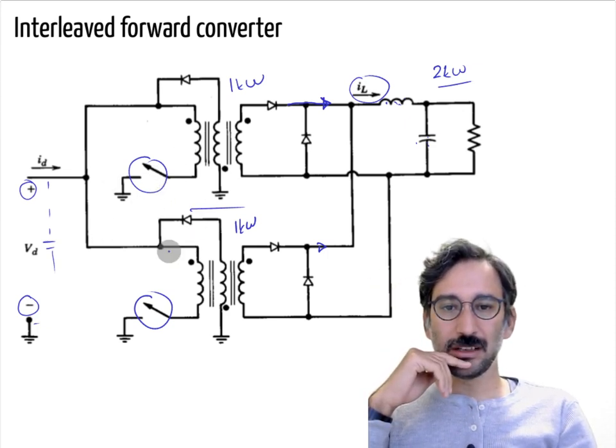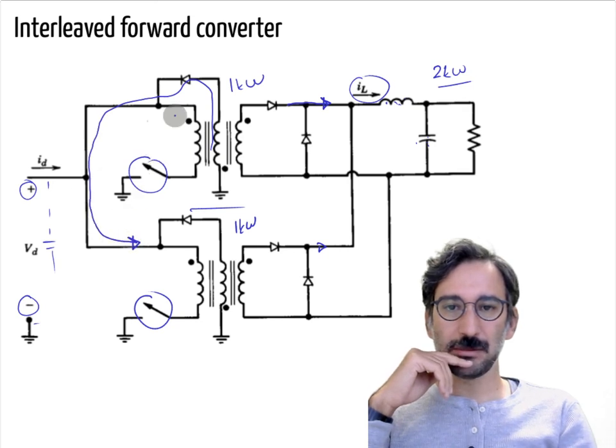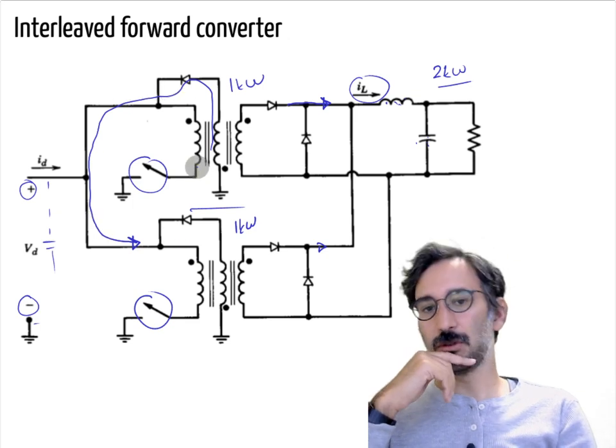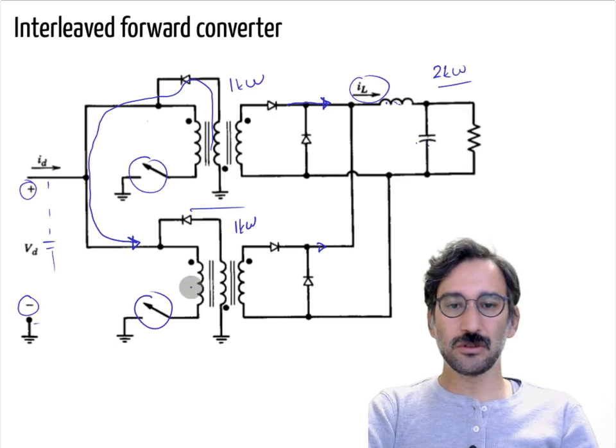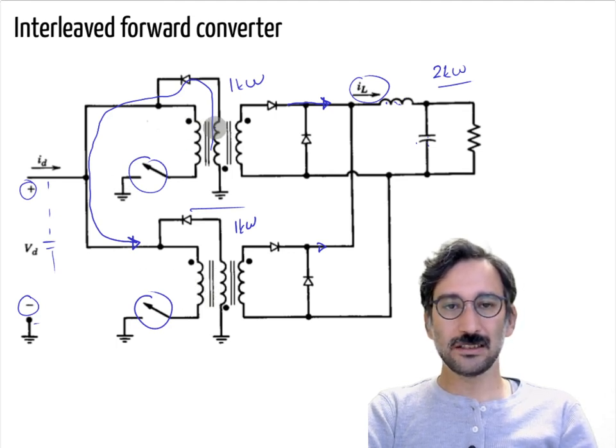Whenever you have a phase difference between these two cores, when one third winding is supplying power, the other one is drawing that power, and vice versa. So instead of sending all the power back to the grid at every switching instant, you store energy on one core, then send that energy to the other core, so the energy is transferred between the two cores without going back to the source.